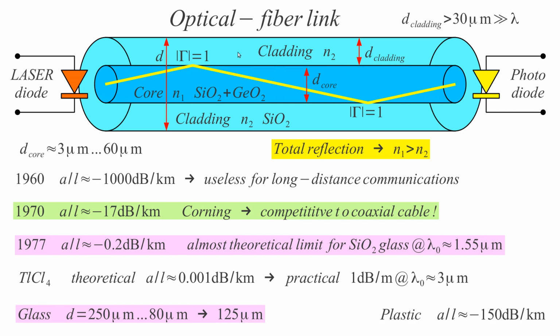How do we guide the radiation over such a device? We guide the radiation by using two different refraction indices. A lower refraction index N2 in the cladding, and a higher refraction index N1 in the core. If we carefully select the angle of the ray propagating through such a structure, we can obtain a total reflection on each of these transitions, core to cladding, so N1 to N2. If the angle is shallow enough here, we obtain a total reflection.